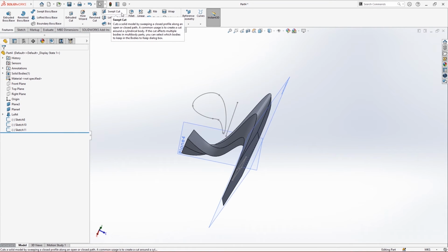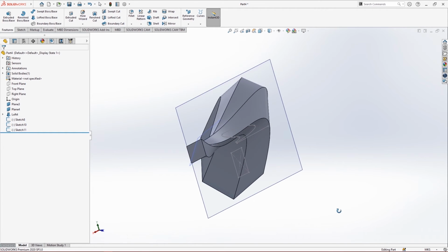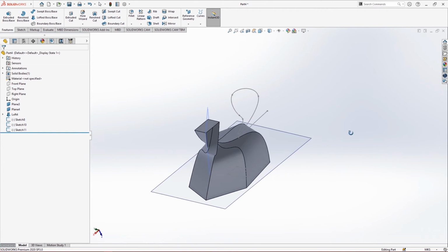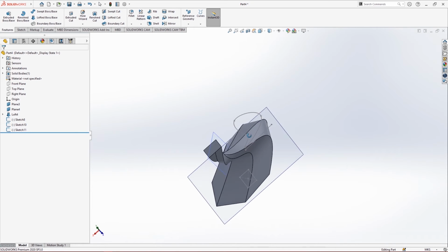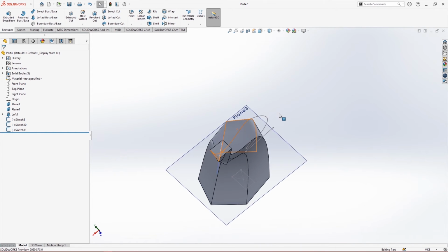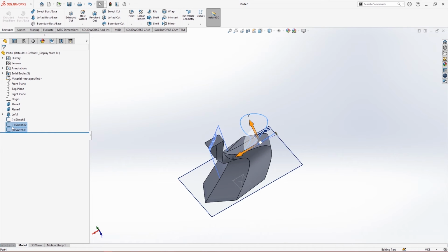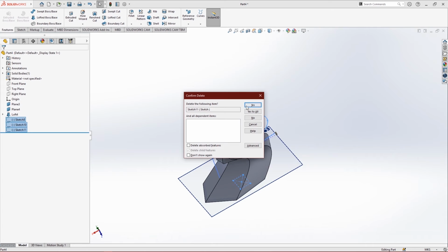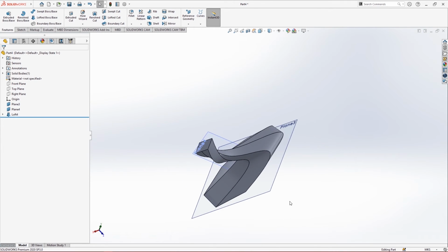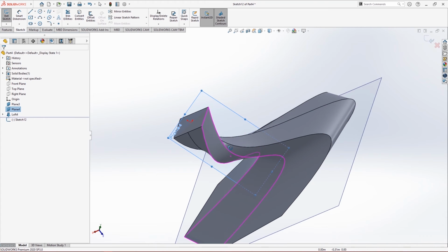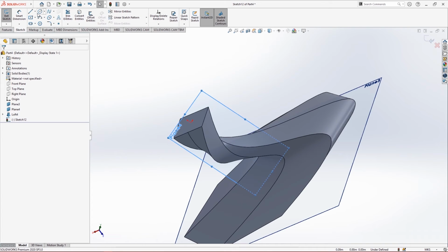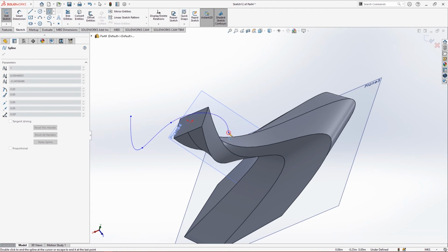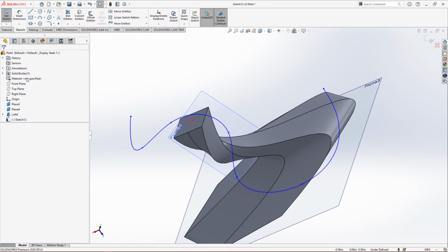Okay, the next thing is swept cut. So the swept cut is pretty much simple. You make a surface anywhere and you can cut using the sweep path. So just one example, I'm going to show you that. So yes, let me delete these sketches. Okay, I'm gonna select plane 4 and I will draw a random thing. Actually I choose random figures because that means it can work with anything. So I'm just gonna make a random spline on that plane, and I just leave it slack.